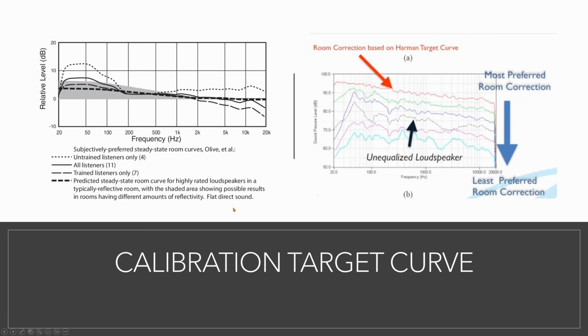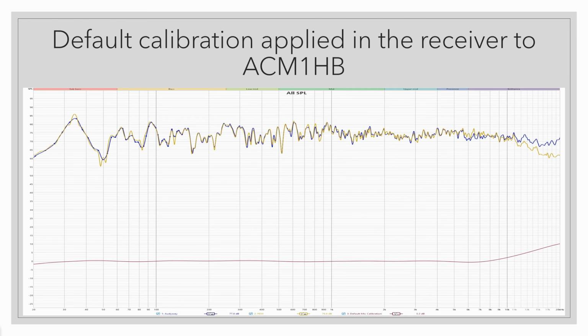If you don't have a calibrated microphone, you can use Audyssey's standard microphone that comes with your receivers. I will provide the calibration file Audyssey batch applies to them. I derived it by comparing an Audyssey measurement hacked from the app with a REW measurement for the same speaker with the same microphone, which was not moved between measurements. And as you can see, most of the response is identical, so it's accurate.